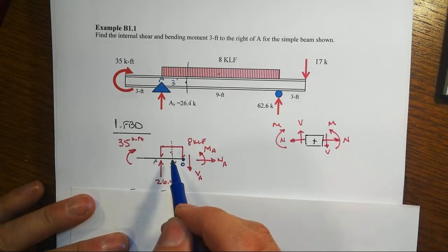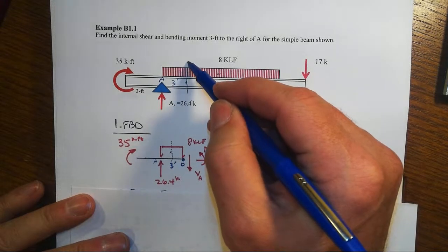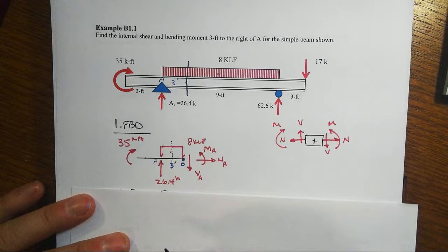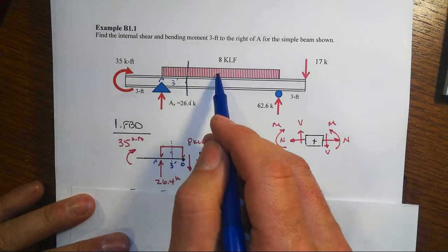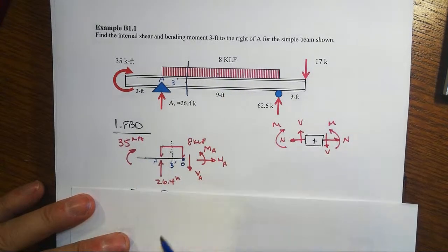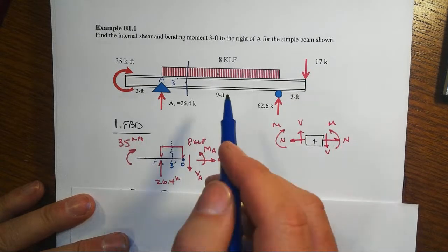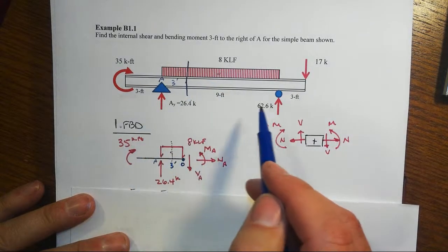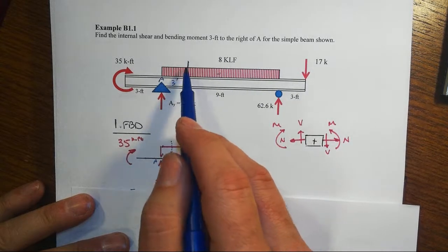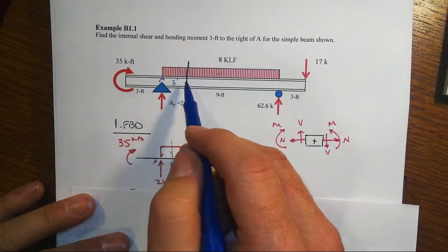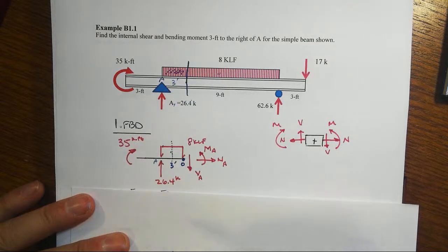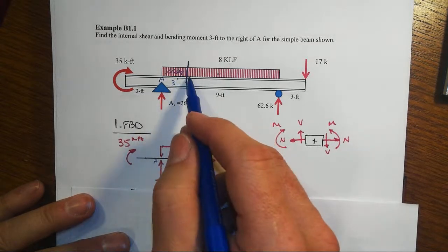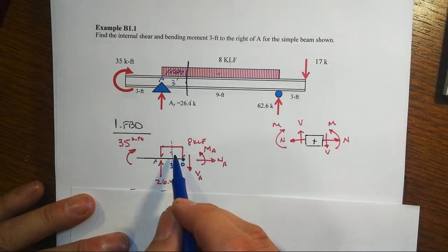and once again must, show the portion of the distributed load that we're cutting through. We are not going to lump all the force here. That would not be statically equivalent internally. It would be statically equivalent to do that for the reactions, but not for the internal. We must include this portion of the distributed load that is in our cut, and that's what you see down here.